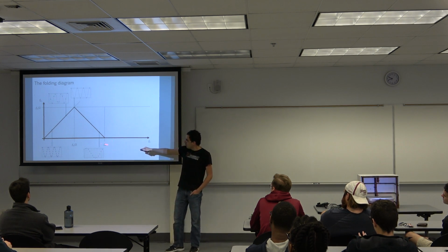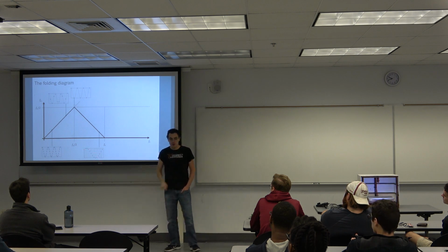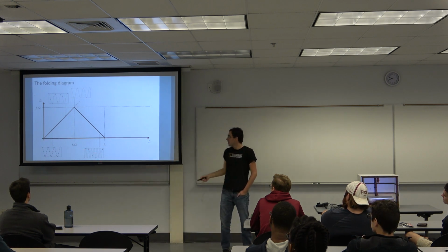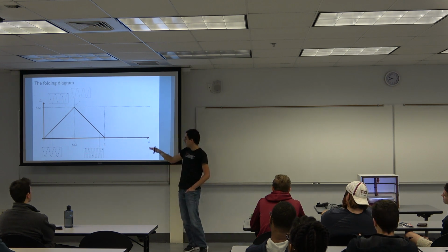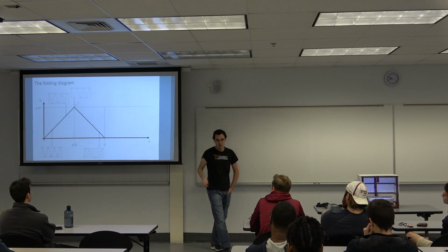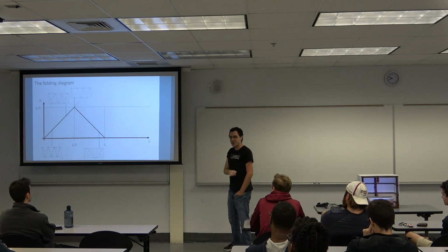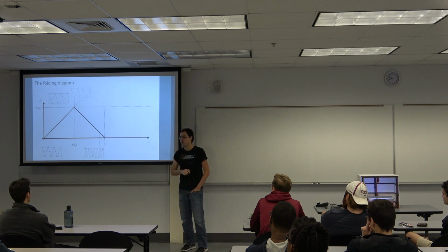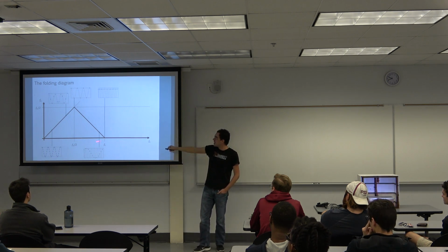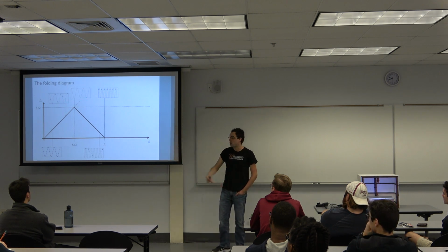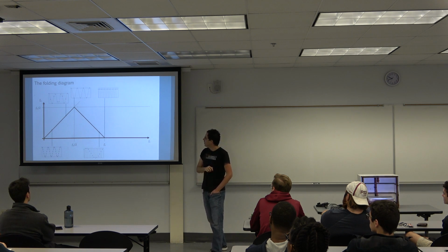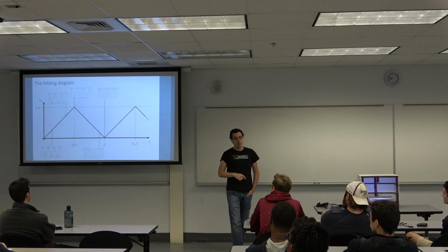If we're between the sampling frequency and half of the sampling frequency, we miss almost a full cycle, which means that the position of the samples slowly drifts, and then we get this low frequency behavior. I'm not going to show what happens over here because it's kind of hard to understand. This one is easier to understand graphically. And if we're sitting exactly at the sampling frequency, then we get 1 sample every phase of the cycle, and that looks like the droplets are just standing still. And this keeps on folding back and forth ad infinitum.